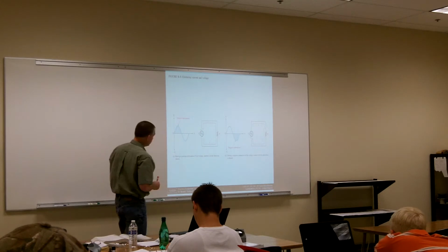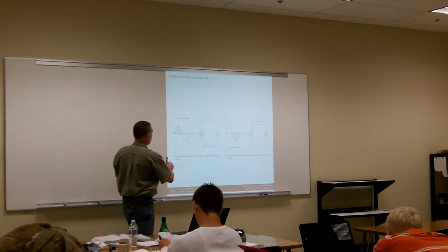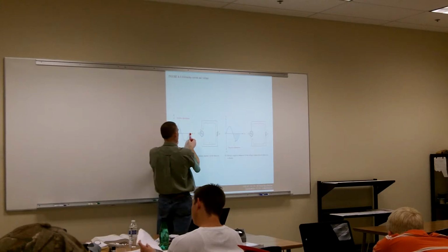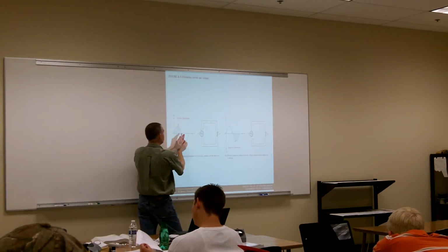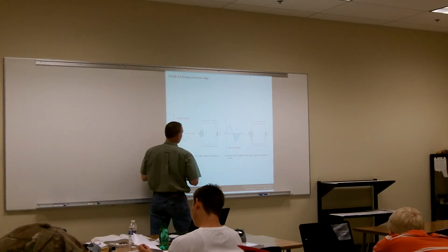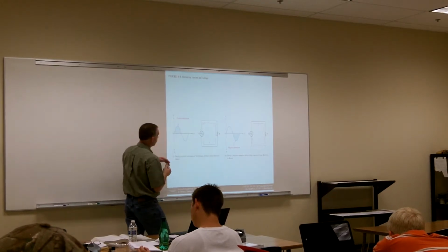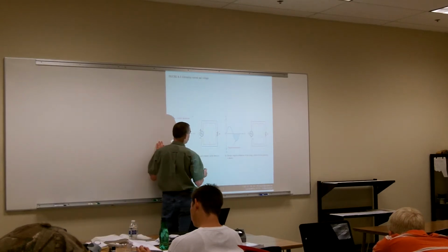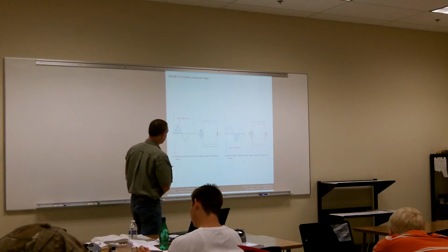When we're analyzing these circuits, we don't look at it as one complete cycle, because that would be too complex. We'd have way too many things going on at one time. So what we're always doing is looking at our positive alternation, and then our second alternation. My first alternation is going to be positive, so my polarity across my function generator is going to be positive, negative.